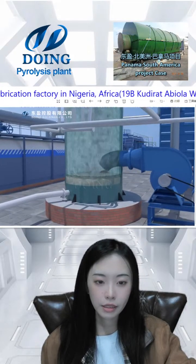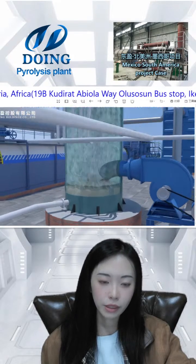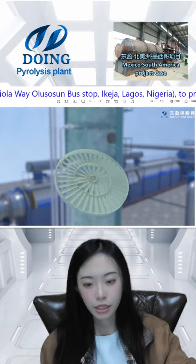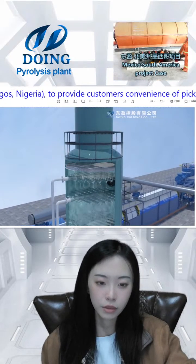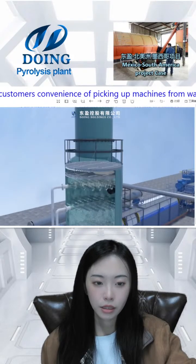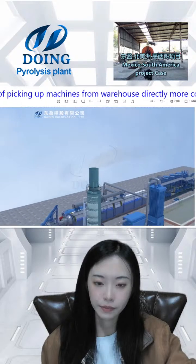The flue gas has been cooled below 120 degrees when it enters this part. And this is the air equalizing device in our tower. It can disperse the flue gas and make it contact with the spraying tower mist more effectively. And this is the moisture removal layer, the demister device.